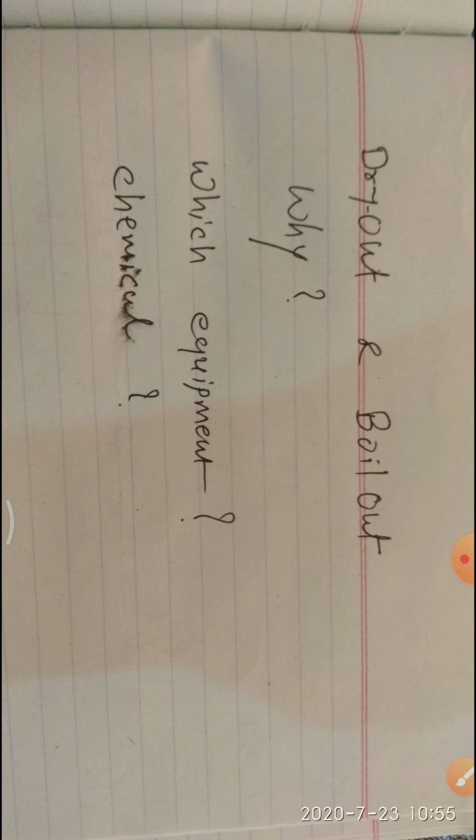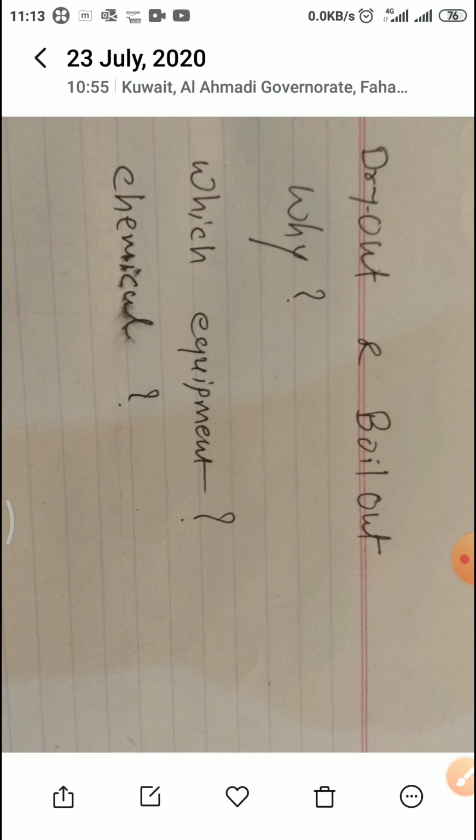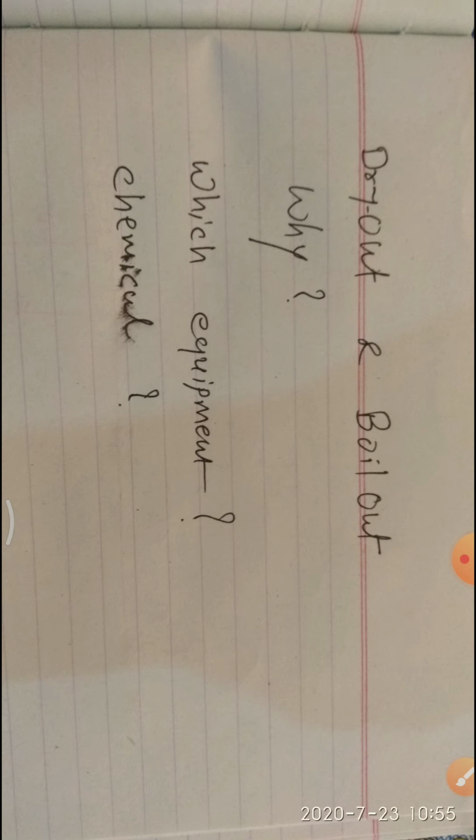When all chemicals are finished, start the reaction furnace pilot or main burner. If a duct burner is available, you can start the main burner, or if other burners are available, you can start a pilot. When starting a pilot or main burner, temperature rises immediately.